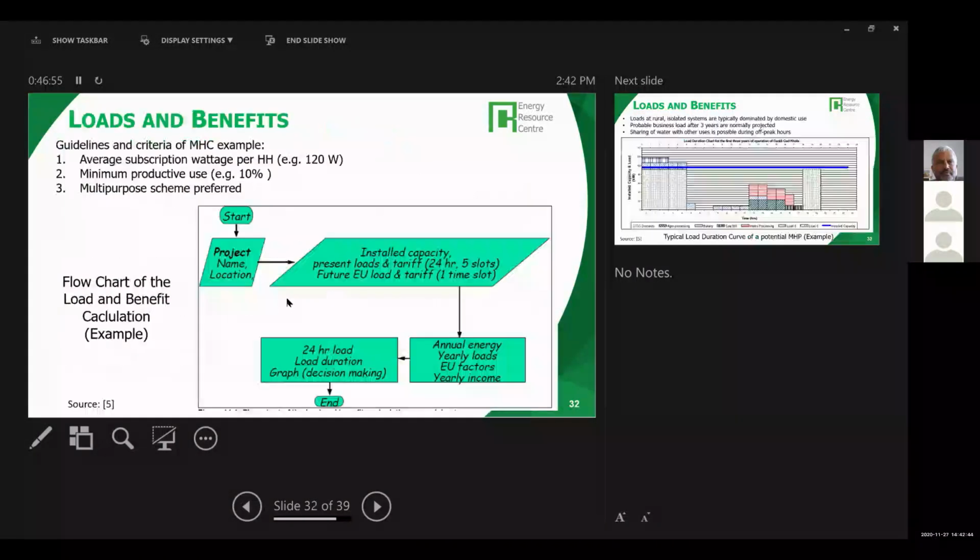financing part. And the other part which is important is, like I mentioned, we will do some exercise in our coming sessions, but I just want to show you how you estimate the load, the demand in a particular community. For micro hydro projects in Nepal, the criterion used is they assume that every household will at least use, let's say, 100 to 120 watts. At least they have 3 or 4 lights. Even poor families can light some bulbs. They have 2 or 3 rooms, and nowadays you have very efficient lighting, so 120 watts.